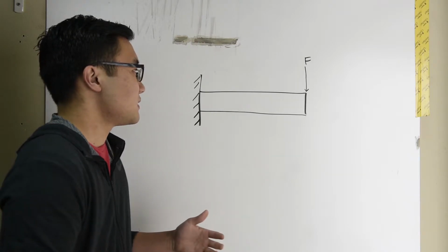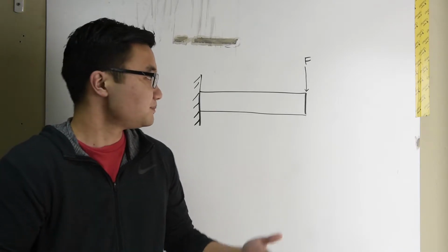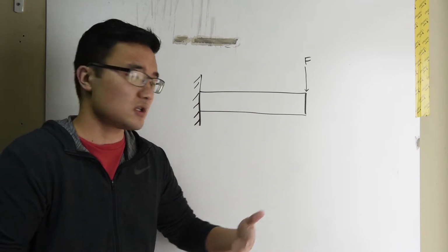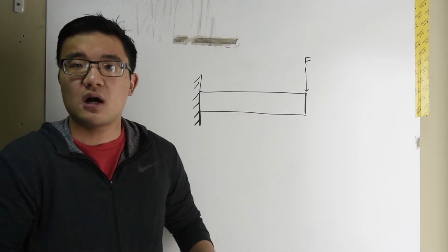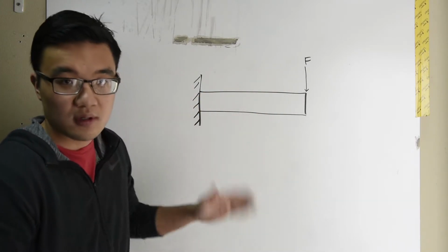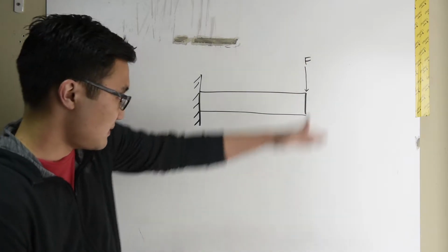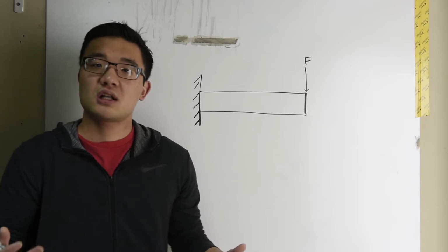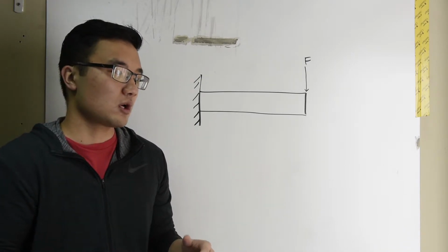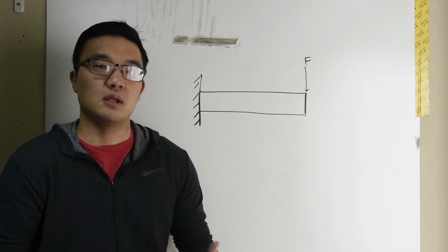And we've already learned that I can calculate the reaction forces under a point force load. I simply sum all of the forces in the x and y direction, and then I calculate all of the moments. For example, this force is acting at a set distance from the support, therefore there is a reaction moment about the support that must resist this, otherwise we'd be pivoting. So we've talked about all of that. However, in real life, we don't typically work with point force loads. We work with what are called distributed loads.